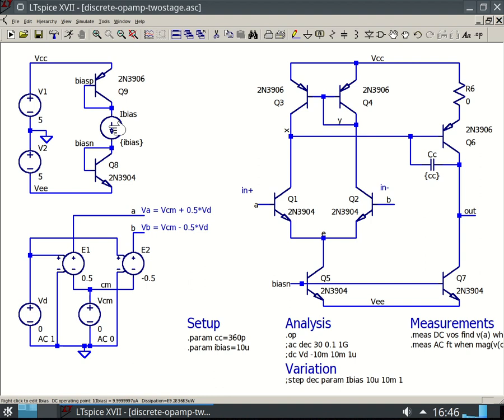The reason it's 99999 whatever is because 10 micro is a number that's less than 1, and remember, we're using floating point numbers. I don't remember off the top of my head if LTspice is using double precision or single precision floating point numbers. Someone can comment and set me straight. Right now it's not important, but that's like a 0.1. We know that 0.1 can't be represented in binary exactly. In fact, it's not representable. It's an infinite repeat. That's why we get the 999.